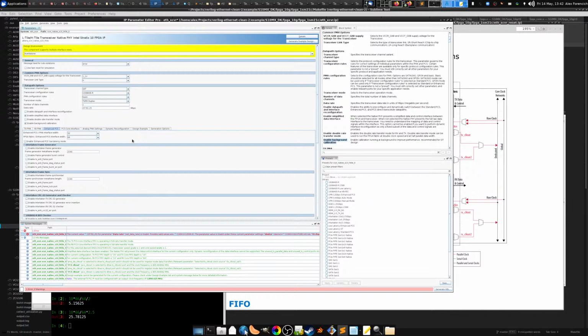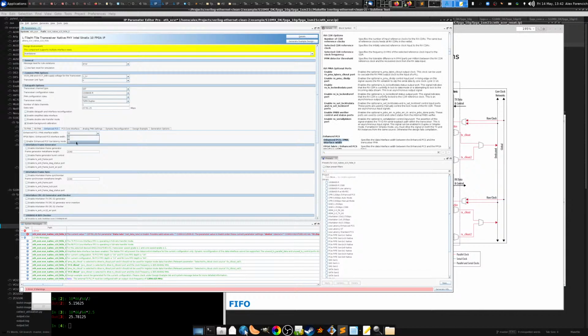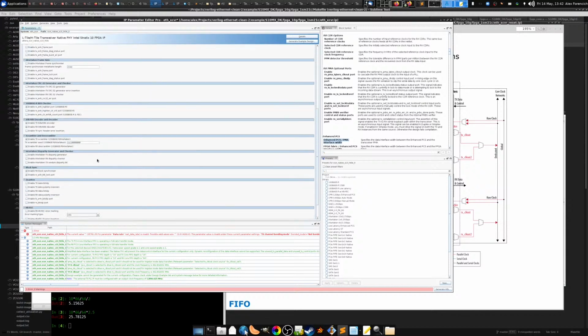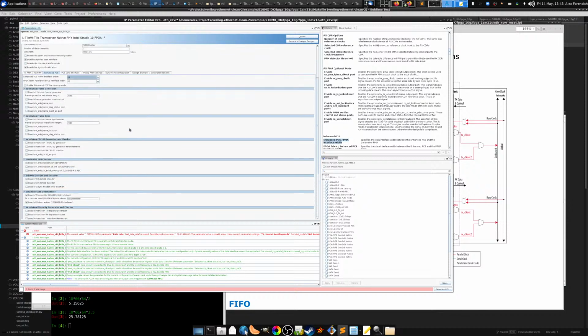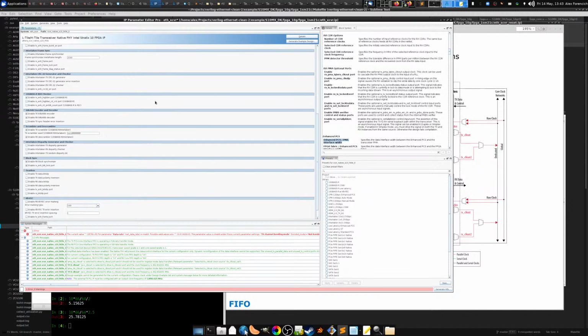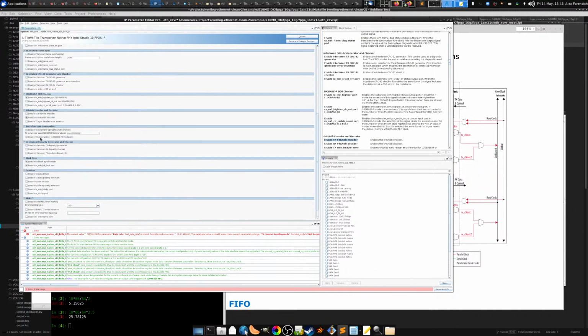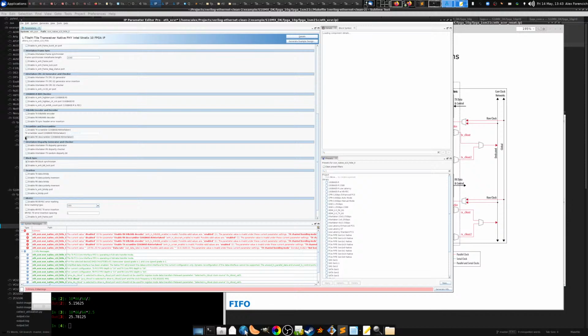So what we need to do now is go into ECS, make some adjustments. I think I need to make that 64, probably. I don't know if that makes a difference. That didn't change much. Okay, let's just start turning stuff off until this works. So with this set to 66, that will turn on the gearbox. Let me try turning off the encoder and the scrambler, and we'll see if that helps. Okay, so that is now giving a different set of errors. Still not happy about something. I think it has something to do with the FIFO settings.